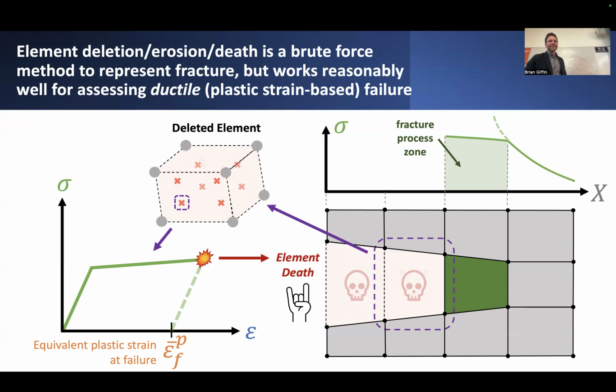And in general, element deletion is not a great option if these elements were otherwise carrying some amount of stress, because you kind of want those elements to dissipate all of that fracture energy, right? If you just said, oh, it reached this critical stress threshold, delete those elements, you'd be getting the fracture energy wrong. You need to at least have dissipated the correct fracture energy before you delete these things.